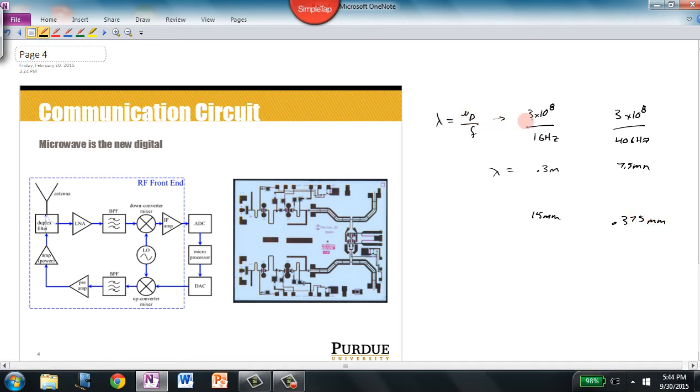And this is in free space. These cutoff lengths for the transmission lines, where we have to switch between lumped and EM analysis techniques, would be even smaller when we consider that this is traveling in a conductor. And we'll talk about how the conductor and the material in a microstrip circuit actually affects that.